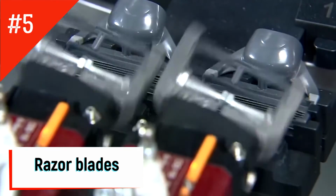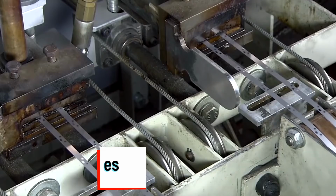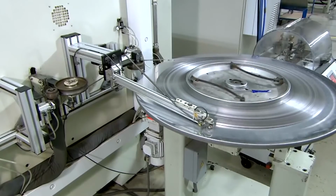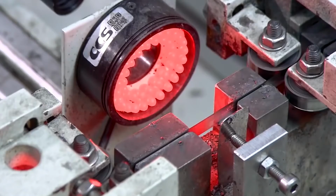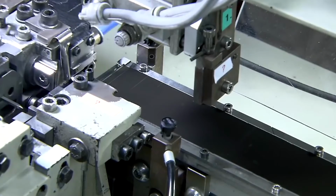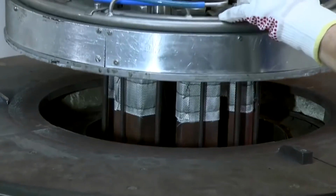Razor blades. Production of razor blades begins with metal processing. The metal strip passes through a furnace in which it is heated up to 1000 degrees Celsius. Then the strip is cooled and then heated again. These sudden changes in temperature change the molecular structure of the steel, making the material more solid and durable.